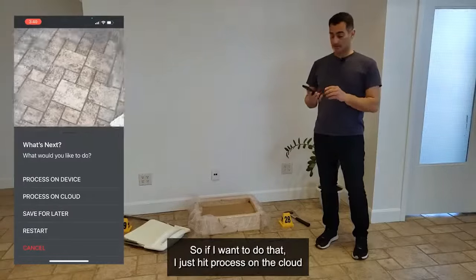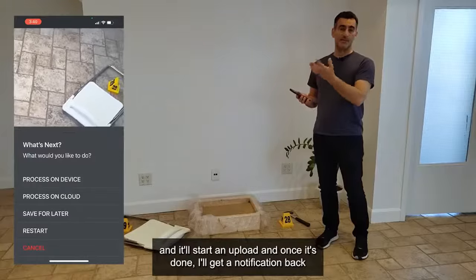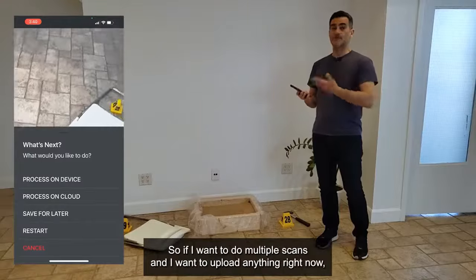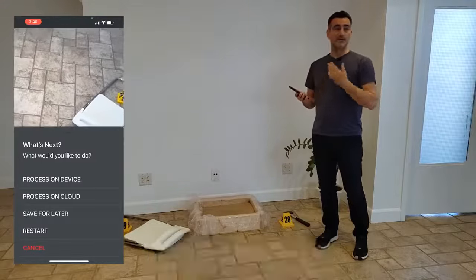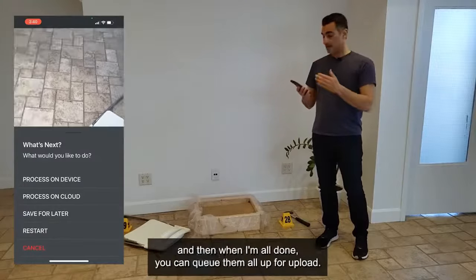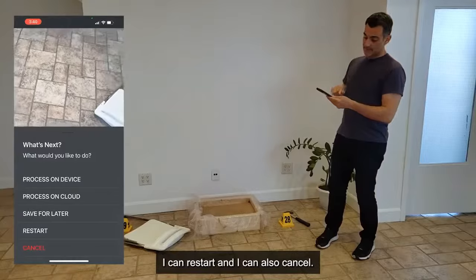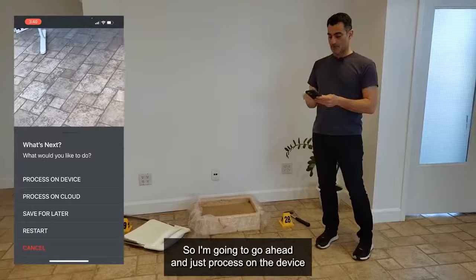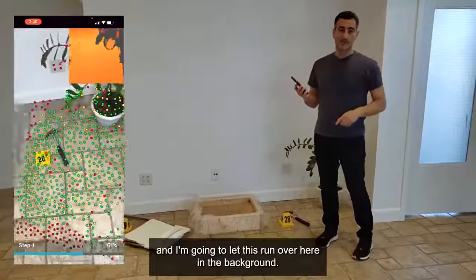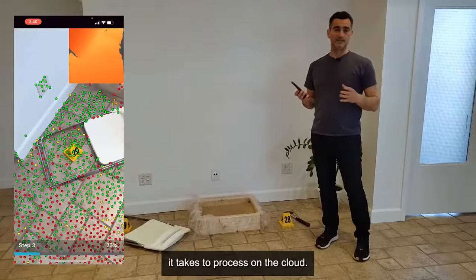Process on the cloud. So if I want to do that, I just hit process on the cloud, and it'll start an upload. And once it's done, I'll get a notification back that it's complete, and save for later. So if I want to do multiple scans and I don't want to upload anything right now, I can do multiple, just go save for later, scan again, save for later, scan again. And then when I'm all done, you can queue them all up for upload. I can restart, and I can also cancel. So I'm going to go ahead and just process on the device, and I'm going to let this run over here in the background.